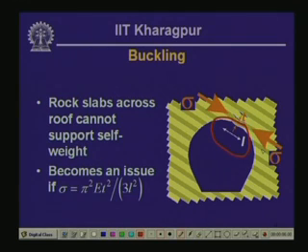That is the area where the tunnel is going to be affected by the buckling problem. Because of the excavation of the tunnel, the confinement to the rock slab has been removed, and because of that the rock slab can no longer resist the buckling tendency that arises because of the presence of the in plane compressive stress sigma, and consequently the slab buckles into the opening.